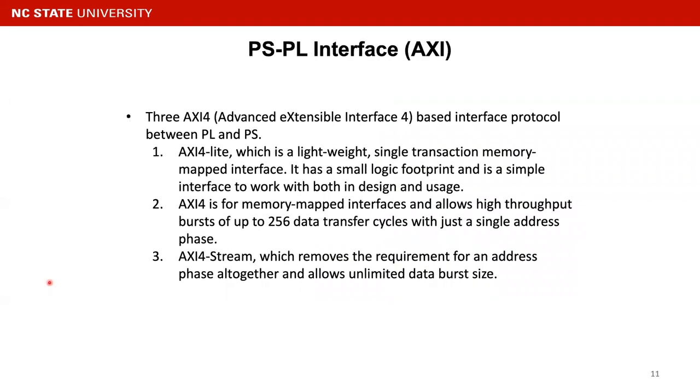Moreover, as mentioned before, since the SoC has two parts on one chip, one for PL and one for PS, there is a need to have a very high performance interconnection interface between them. So the Zynq 7 SoC has three AXI4 based interface protocols between the PL and PS.